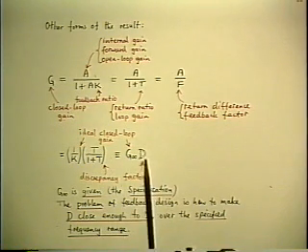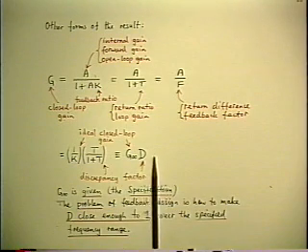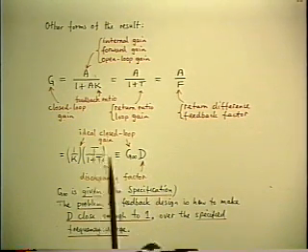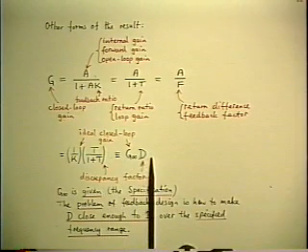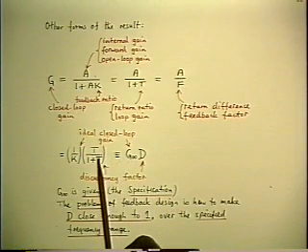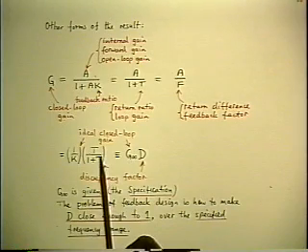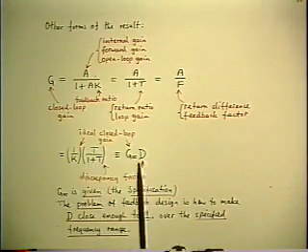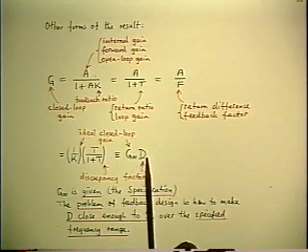As I mentioned in the introduction, you're certain to have a problem at the high frequency end because t will always go to 0. You may have the same problem at the low frequency end because if the amplifier is AC coupled, then t is going to go to 0 at 0 frequency as well.